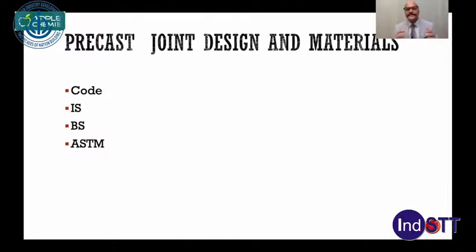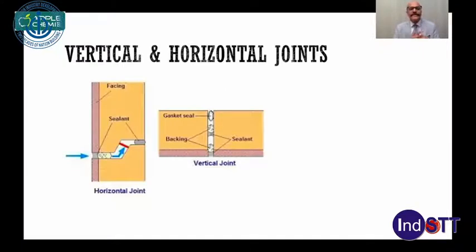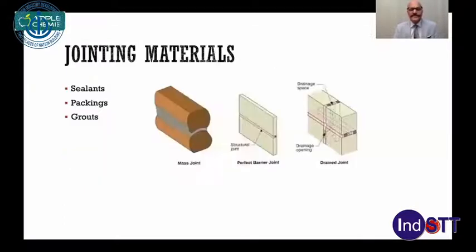I am not discussing that here, but what I am discussing is the challenge and how to meet the practical challenge. See, the joints can be categorized basically into vertical and horizontal segments, and then you have a mechanical connection between the two joints, and then you have sealants and adhesives and protection coatings, and protection strip seals coming on the surface, which we can call a weather strip, and then the sealants are polyurethane sealant or silicone sealant and many other things.